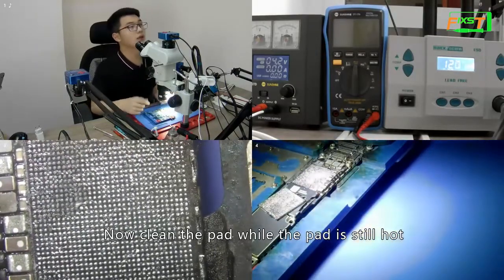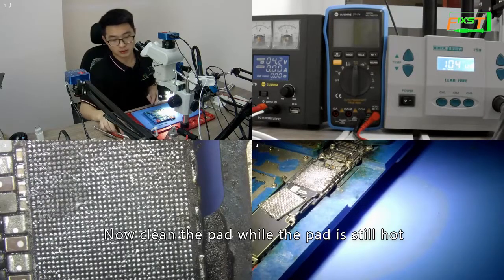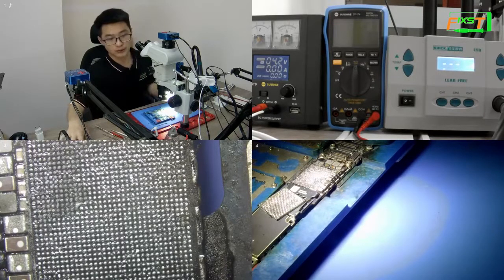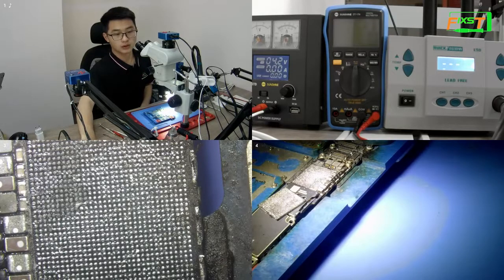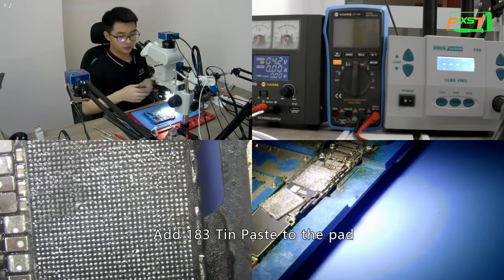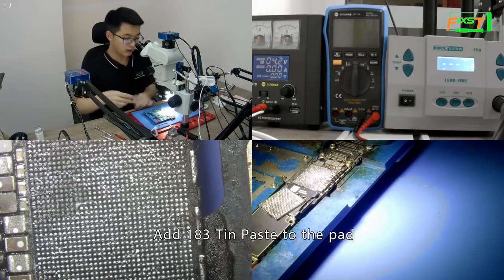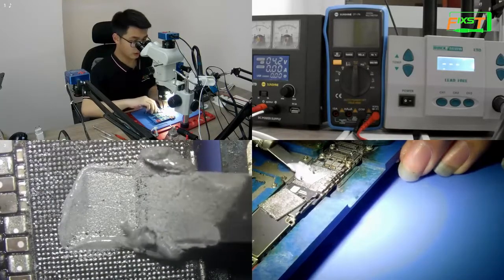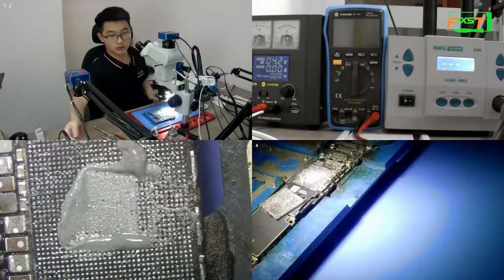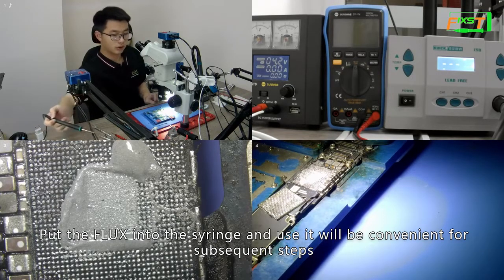Now clean the pad while the pad is still hot. Add 183 tin paste to the pad. Put the flux into the syringe, which will be convenient for subsequent steps.